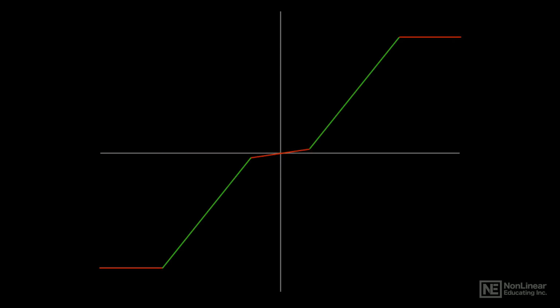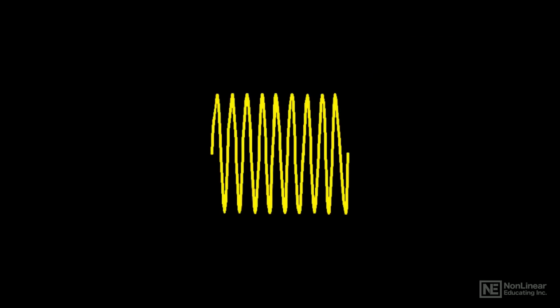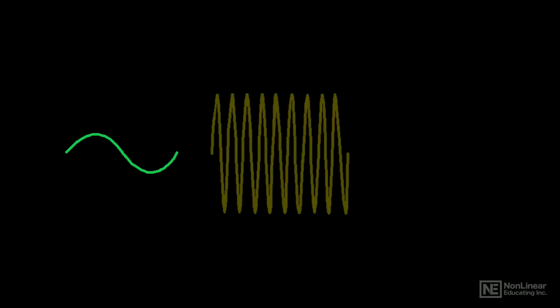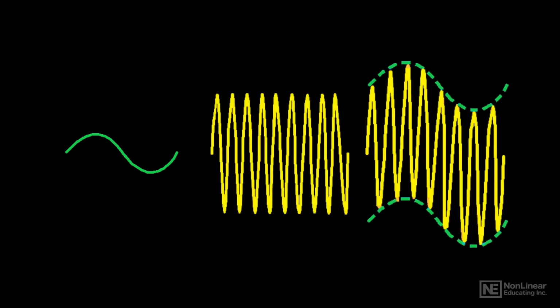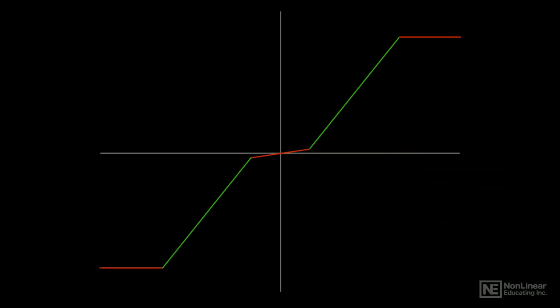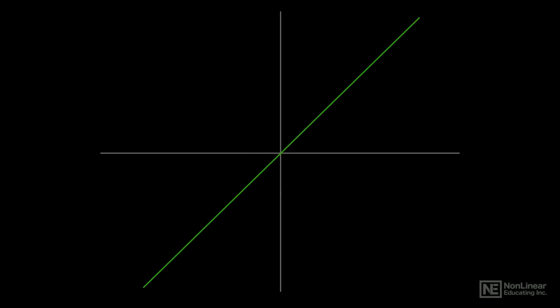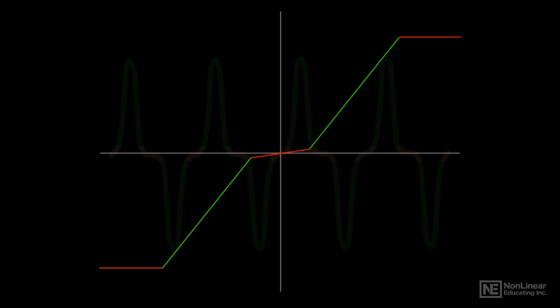To remedy this, an inaudible, high-level, ultrasonic, high-frequency signal is recorded on the tape along with the audio signal. This is called the bias frequency. The combination of the weaker, low-level audio signal and the stronger, inaudible bias signal provides strong enough magnetic flux to allow for linear recording of the low-level audio, reducing the otherwise objectionable third harmonic distortion.